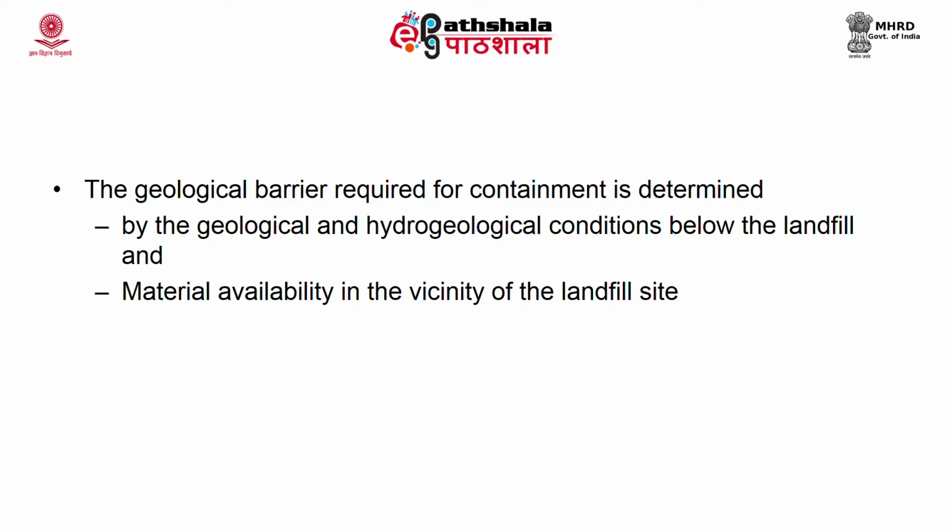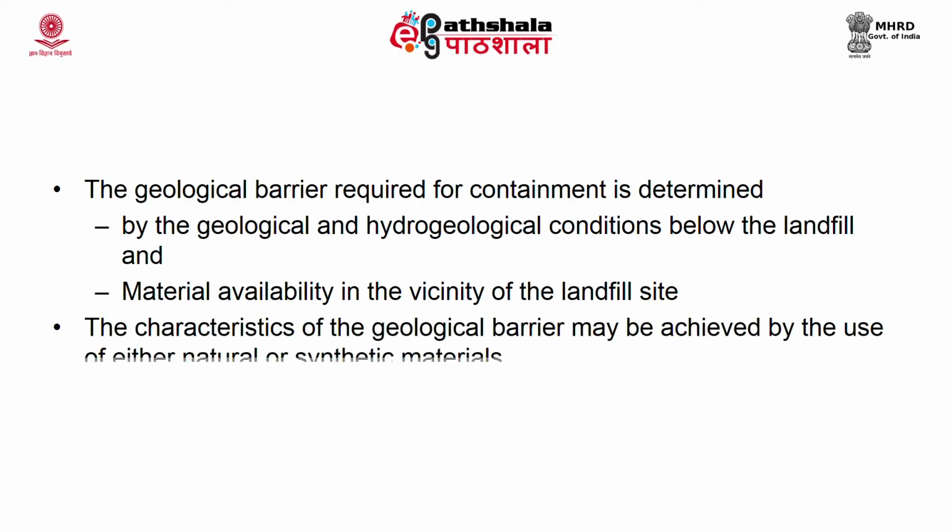Now, hydrogeological conditions include the groundwater table, the hydrological isolation, and the distance to the water body. These factors are considered under hydrogeological conditions. The characteristics of a geological barrier may be achieved by use of a natural or a synthetic material.